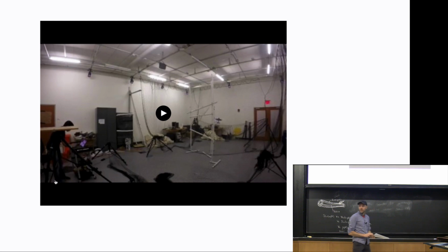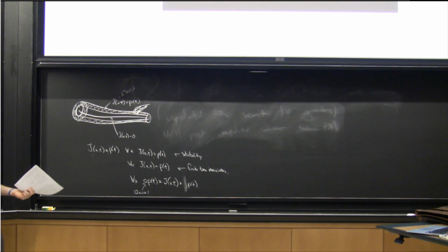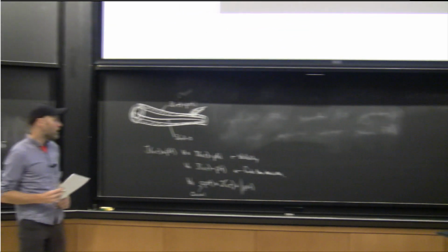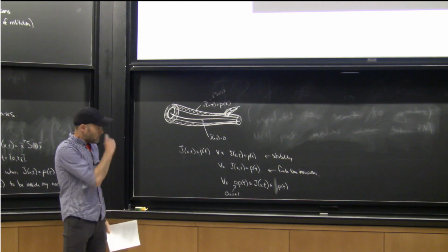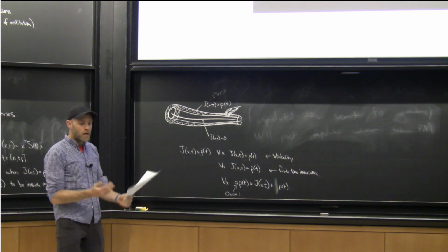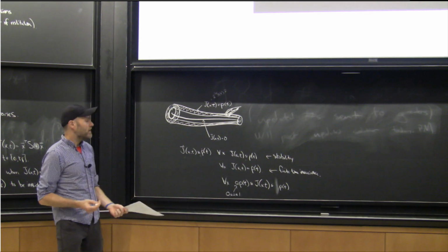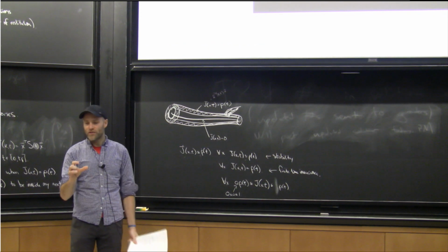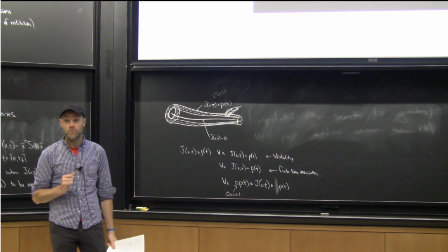Okay, so if I had more time, let me just tell you what I didn't tell you. The last piece of this puzzle is that the number of funnels you end up adding roughly depends on how well your LQR controller works for the nonlinear system.